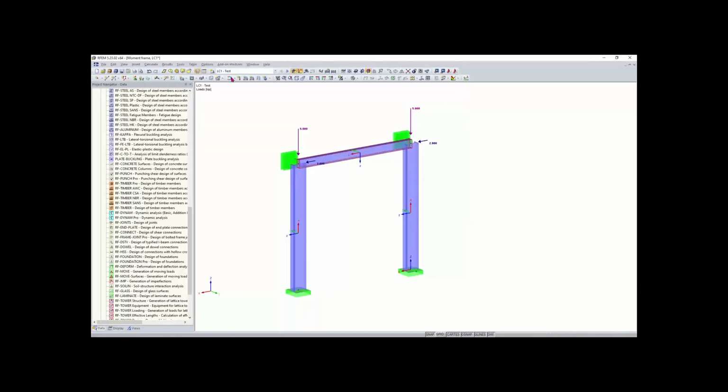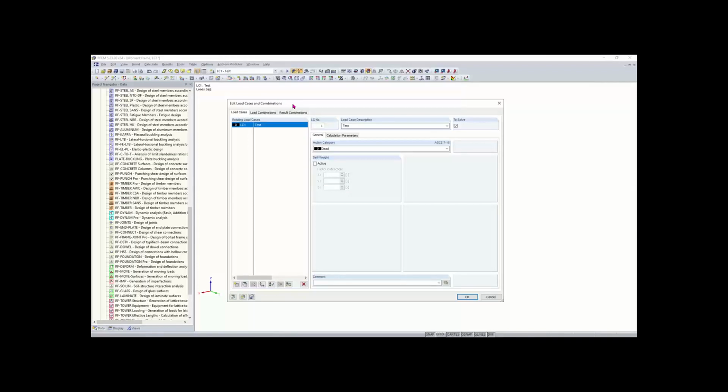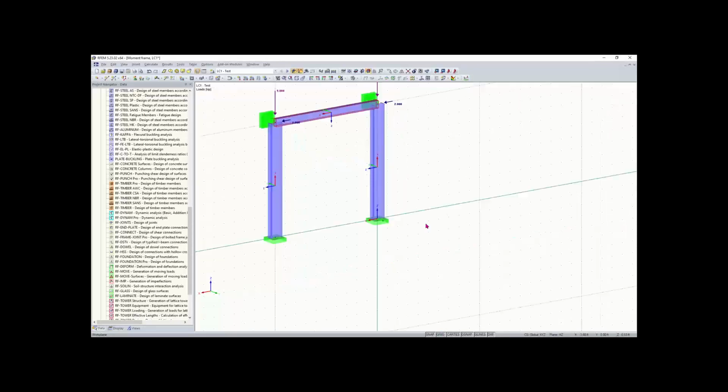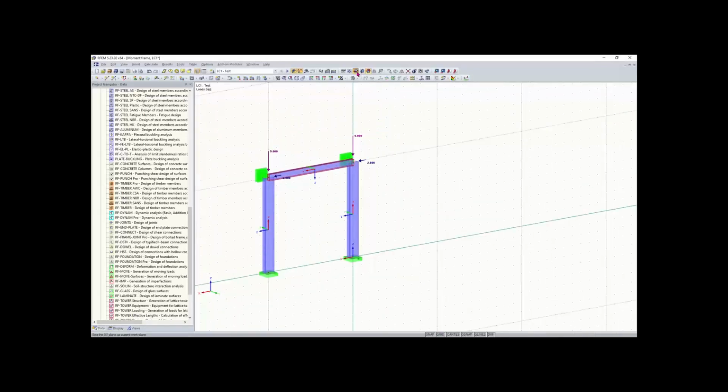Yeah. So basically, like Amy said, those are for pitched roofs on rectangular buildings, but you can also just create a new load case, create your wind load case, and add in your lateral loads or lateral uniform loads as well. So good. Another quick question, going back to the beginning: when you create a new line or a new member, how do you modify it if you notice your dimensions are not accurate?